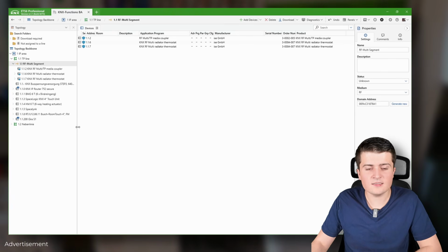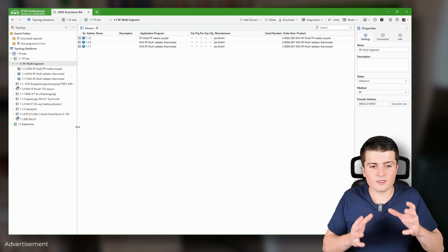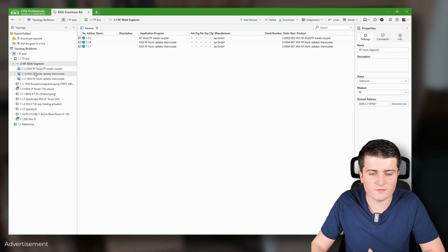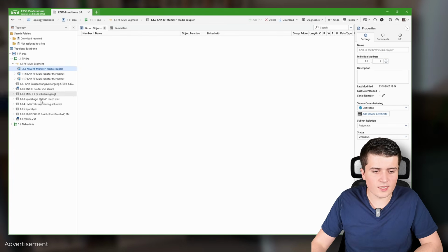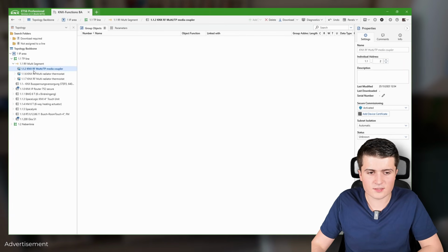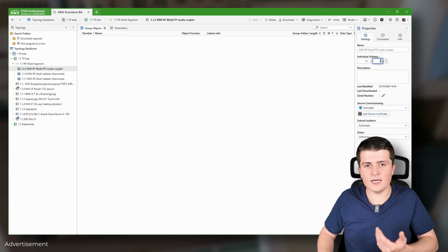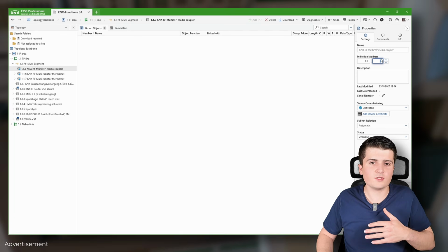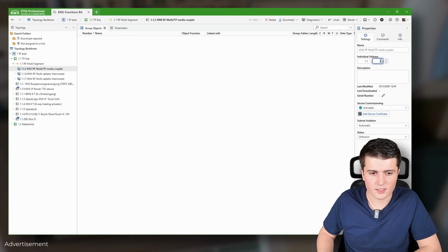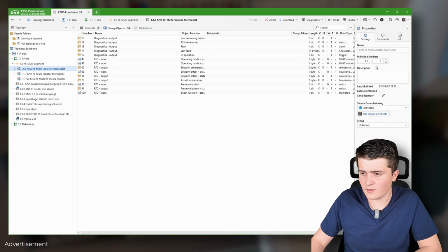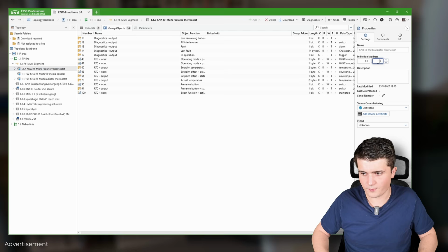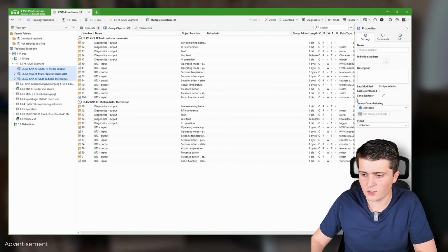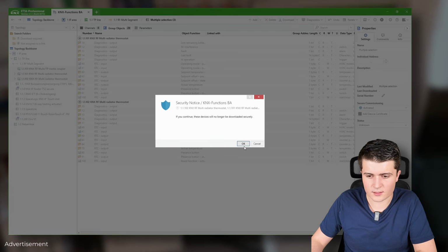And now here in my case, I want to have those segment devices, so those RF multi devices, in sort of one physical address range. Because normally, as you see here, they just use the next free address it sees in my installation, but I instead want to have it, for example, at the address range 100. So all the RF multi devices then start with the address 100. So the multimedia coupler 100, then the first radiator 101, the second one 102. And as I don't want to use the secure communication, I disable it here.